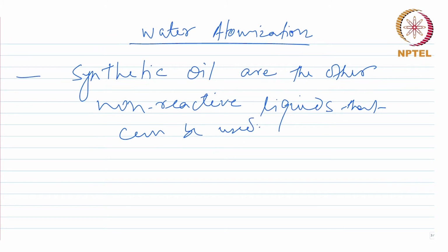Right. So, as long as the liquid does not react with the molten metal, it can be used as a jet to atomize the molten stream of metal and make those fine droplets which will solidify as metal powders. And at times these synthetic oils can have better control on particle size and oxidation.